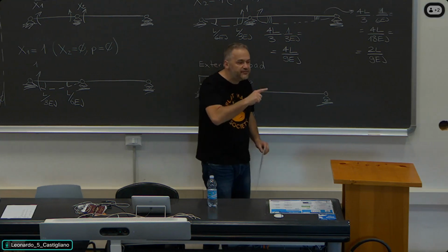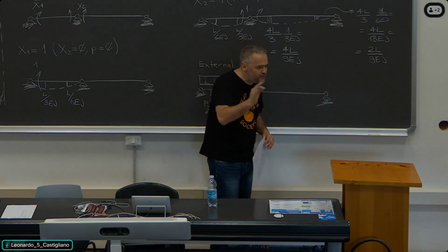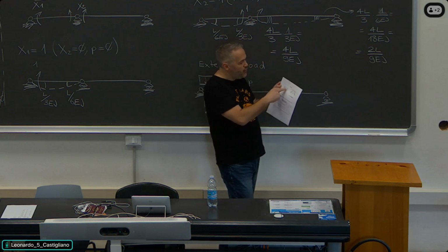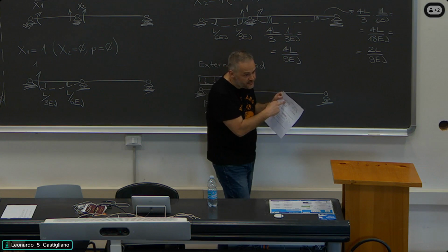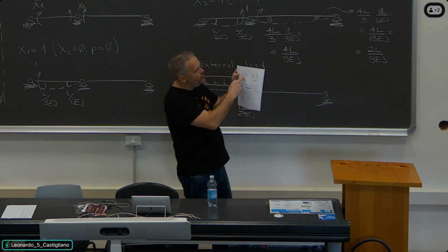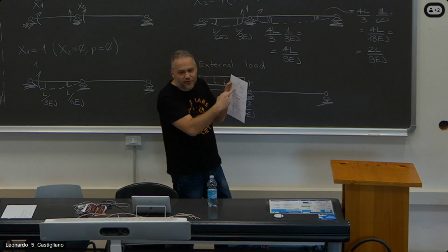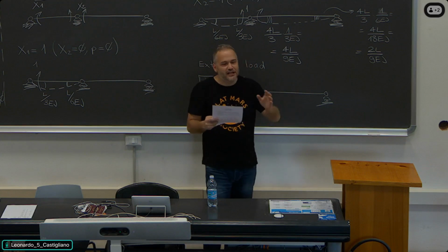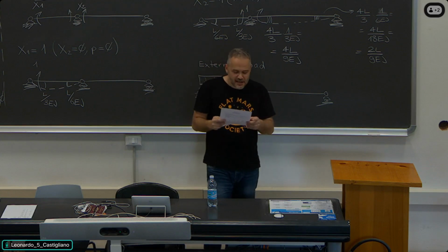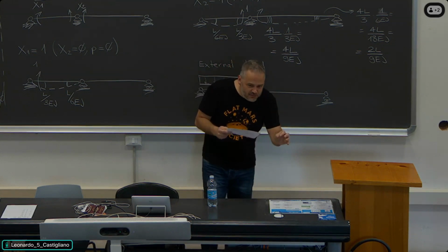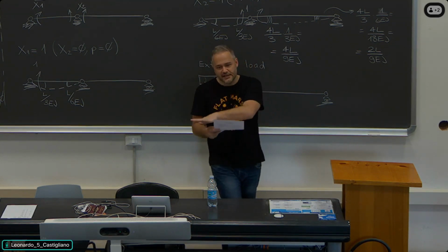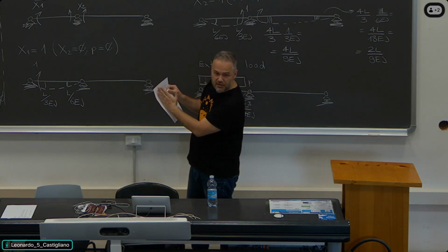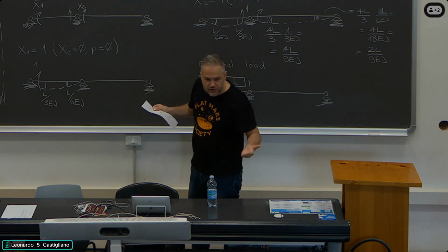No, that's what I said previously. It's not a matter of left or right. Physics does not care about left or right. That's a convention. Physics cares about where the bending moment is. So, again, when you look at this coefficient, you should not look at it in the way of the left rotation and the right rotation. You should look at the rotation where the bending moment is and the rotation at the unloaded end. If you want it the other way, just put a mirror here and look in the mirror. The coefficient is still valid.